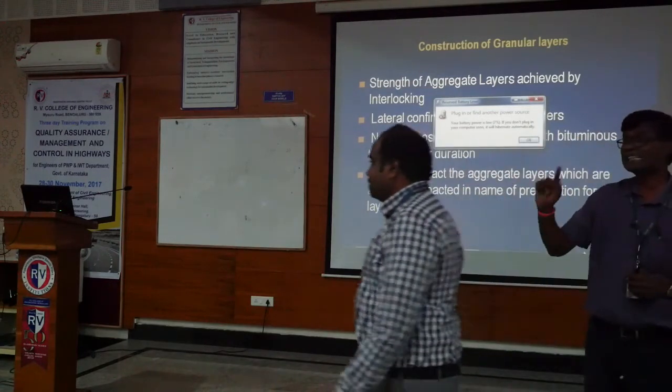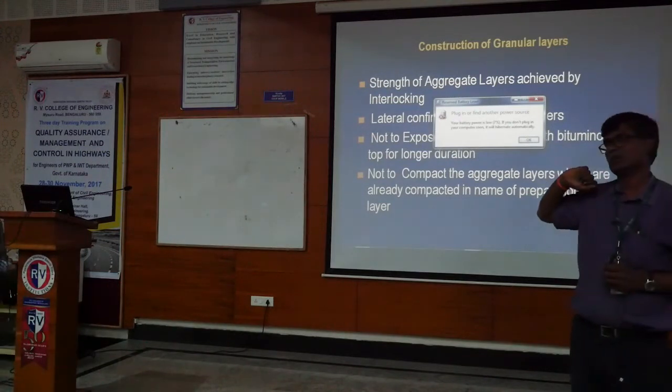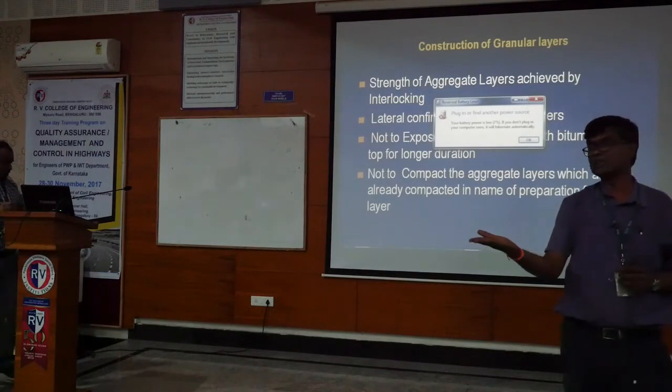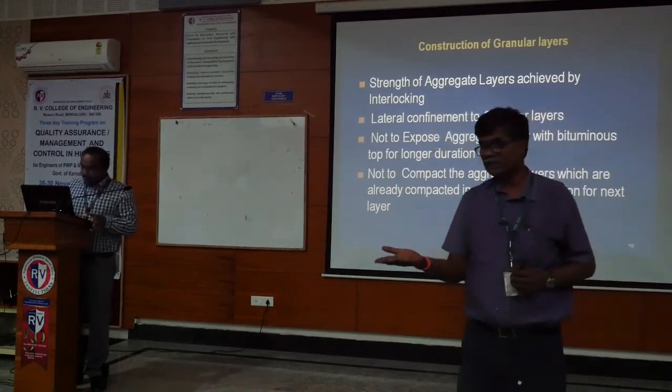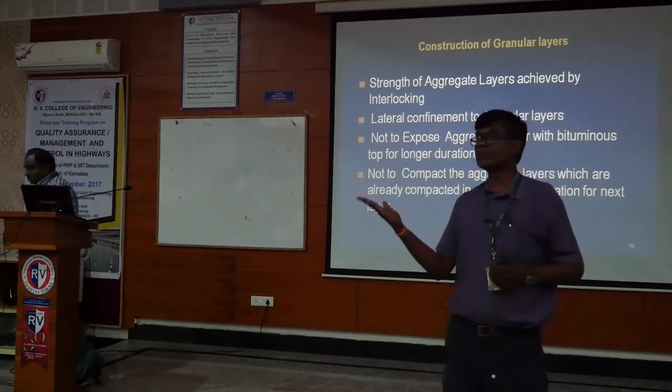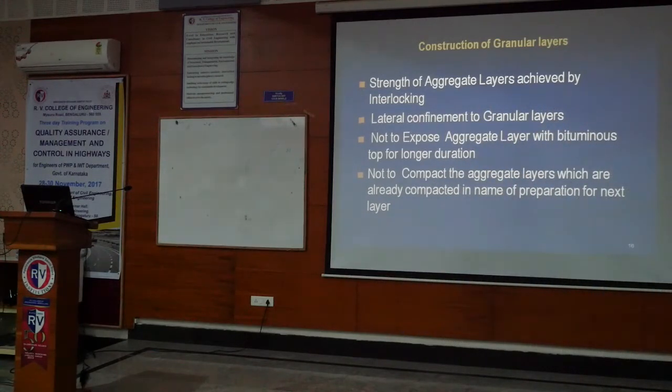That means we are altering the gradation, that is not desirable, that is not desired. To be precise, theoretically speaking, before the next layer goes on top of wet mix, what we expect is the exposed surface of the coarse aggregate before I go for prime coating or interface treatment. What is expected is that the wet mix macadam layer has the aggregate surface exposed. But most of the times there is more interface dust, so that bonding suffers. So these are the two things.